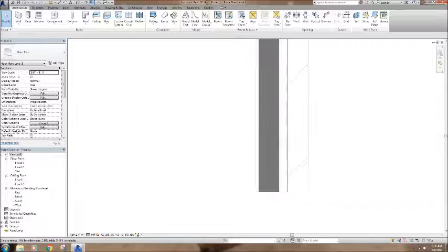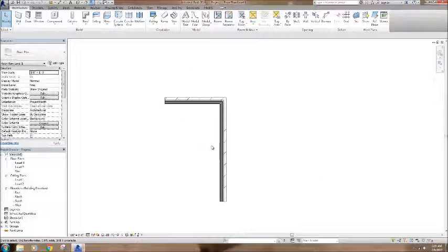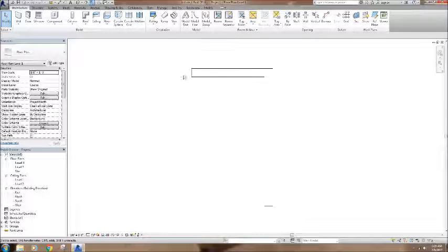Then I've got all of the layers that I just built in here. So I've got my gypsum board, my stud layer, my 7/16 OSB, my 1-inch air barrier, and then my brick on the outside here. So I've just created this wall assembly, and under fine detail I can see all of those. If I go to coarse, it goes back to basically what that 8-inch generic wall looks like. It's not going to show all of the little layers there.